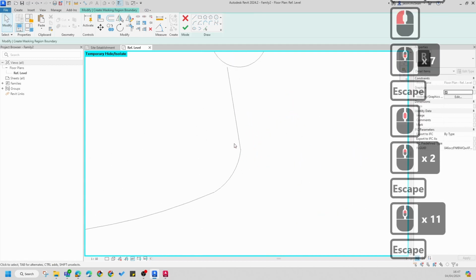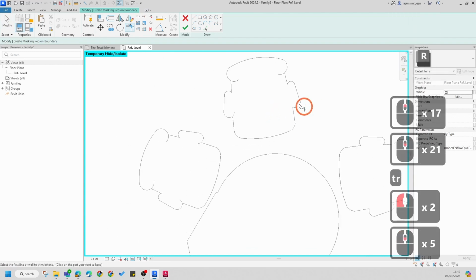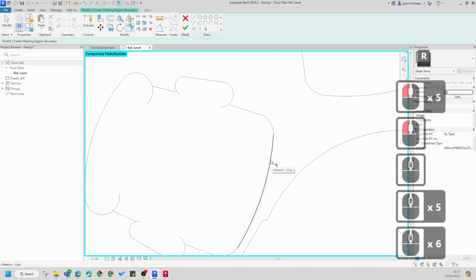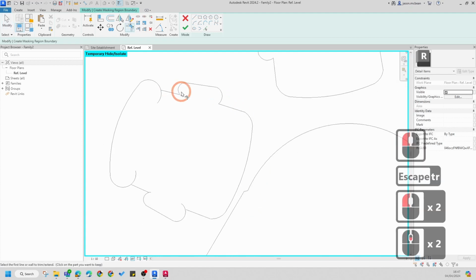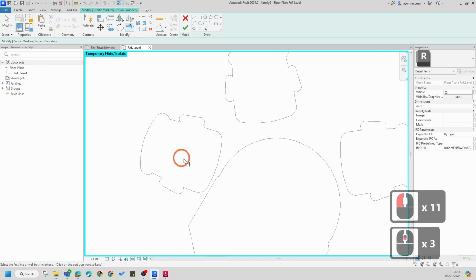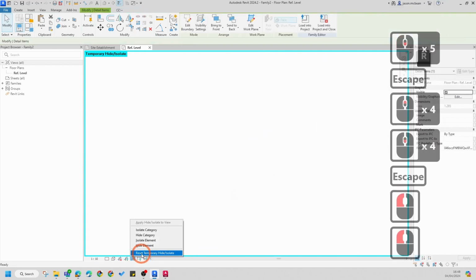Okay, there might be some holes. I'll need to see if there's any holes, but let's just double check. So trim. Trim. But this is quite easy to resolve. Once you've done a couple of these, you'll notice that these things will start working. Trim that, so let's just see here. So trim that with that, trim that with that, trim that with that. Because sometimes AutoCAD files are drawn nice and neatly, sometimes they're not. Okay, good. So if I press finish now, and I go reset.